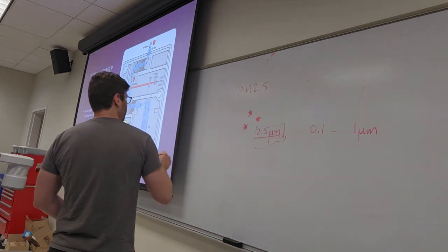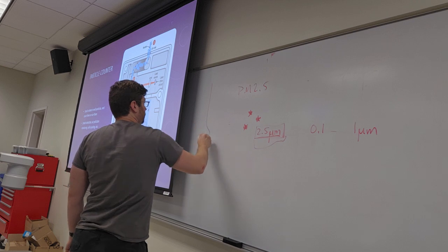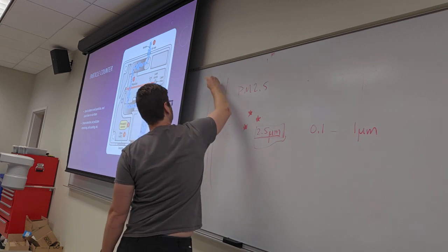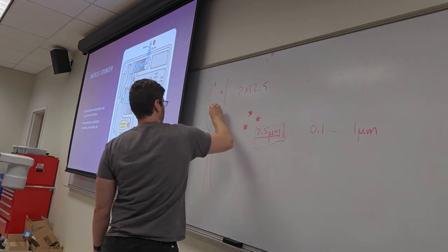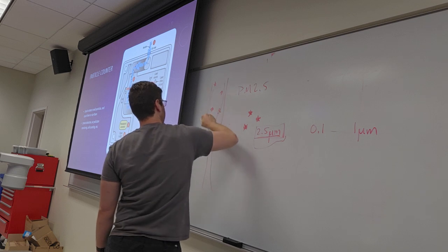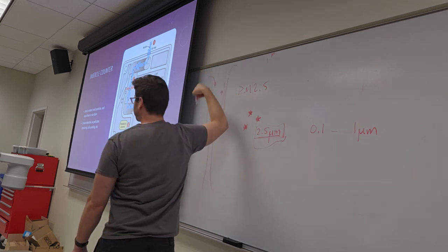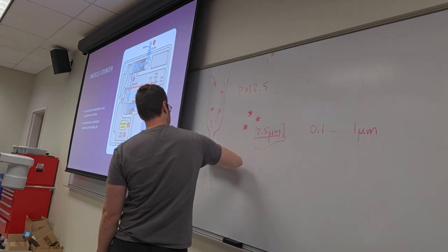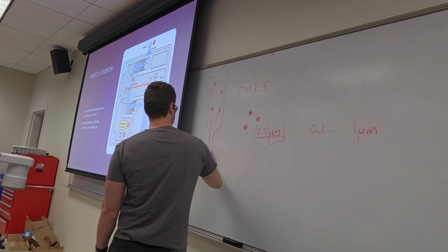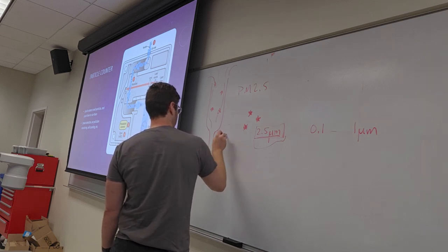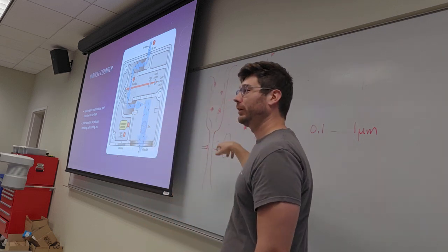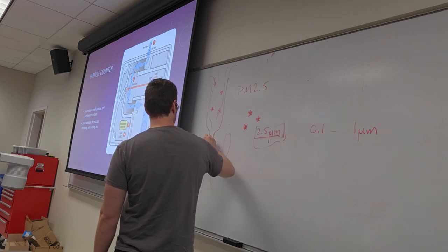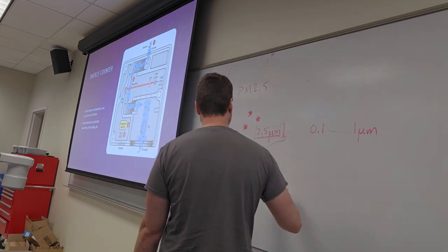The way that we do that is by actually running those particles through a laser. Pretty cool. If we force those particles through an air channel, they all kind of flow into here. This is just sampled air. We have a little pump that draws and pushes air through here, a little fan, right, that pushes it through. If we make it run through a super skinny channel and then shine a laser through that channel, we will get a little shadow puppet show of the particles that run through. The laser will actually briefly be blocked by the particles, and we will see again a one-dimensional graph.